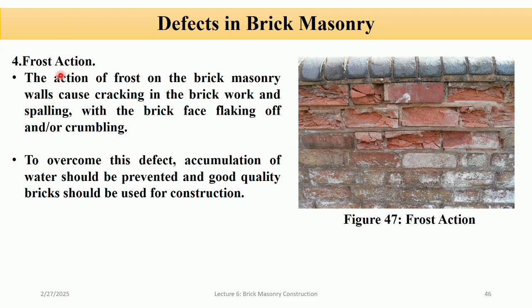Now let's discuss frost action. So frost action refers to the damage caused by the freezing and thawing of water within building materials, especially in cool climate. So the effect of this action is expansion of frozen water in the ground, causing uneven settlements, scaling and spalling, cracking and disintegration, and reduced durability. So in order to overcome these defects, accumulation of water should be prevented and good quality bricks should be used for the construction.